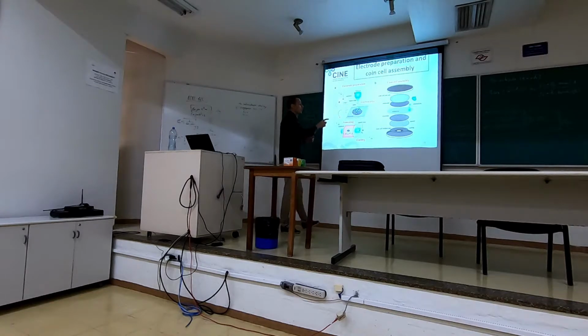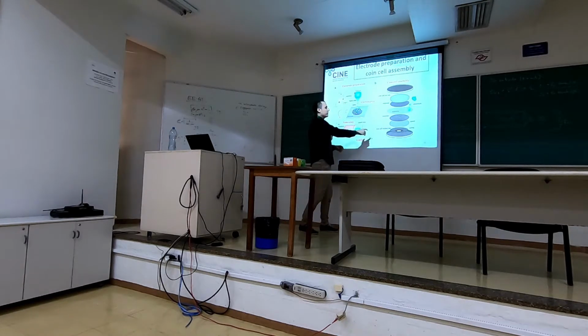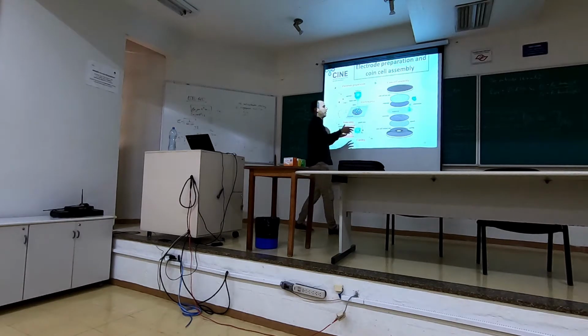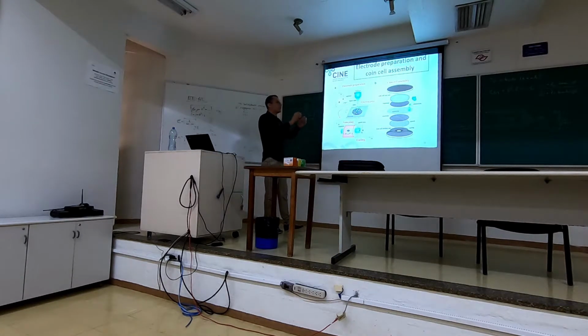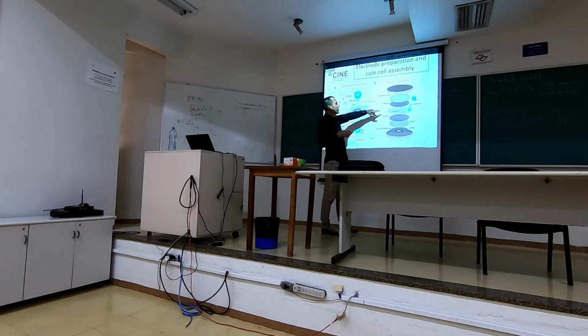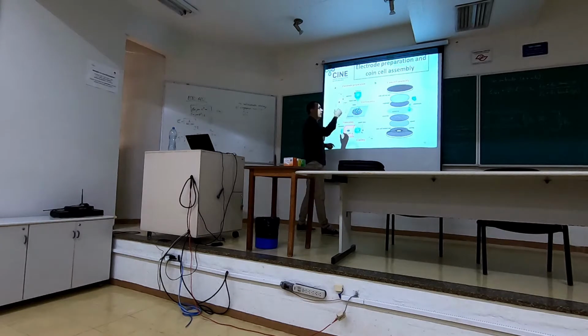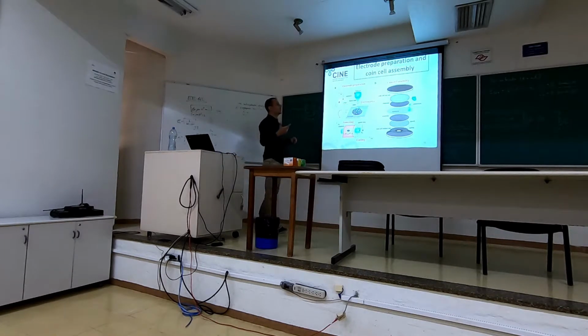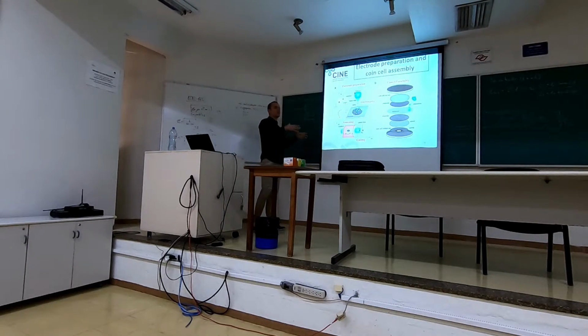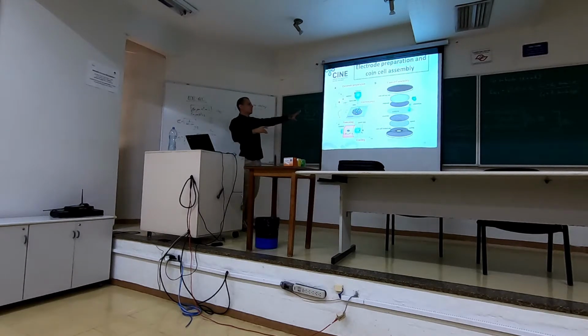In figure B, you can see a schematic representation of the coin cell assembly. In the bottom part, we can see the coin cell bottom cap, followed by a spring and a spacer, with that spacer working like an electric contact, followed by two electrodes separated by a mesoporous membrane, and next we have another spacer, and finally the coin cell top cap that will close the coin cell. Again, this coin cell was used for all electrochemical studies.